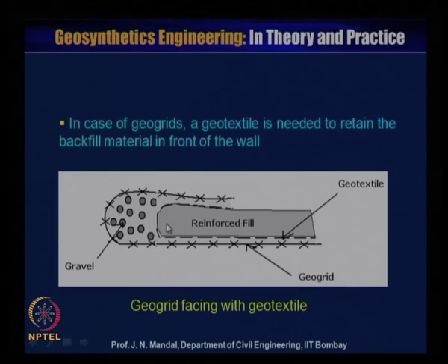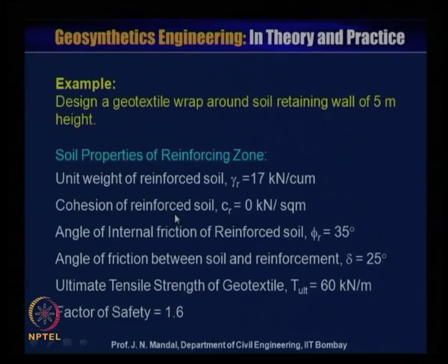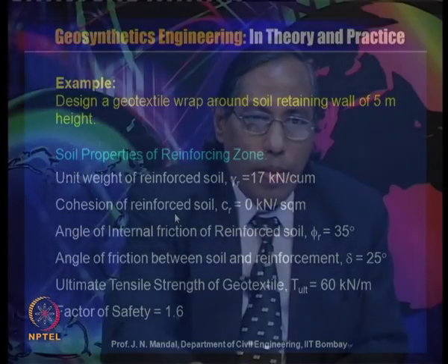This reinforcement fill material should not come out from the geogrid material, and this reinforcement fill material will also act as a separation and as a good drainage material. Also the grass can grow on the back of the wall.